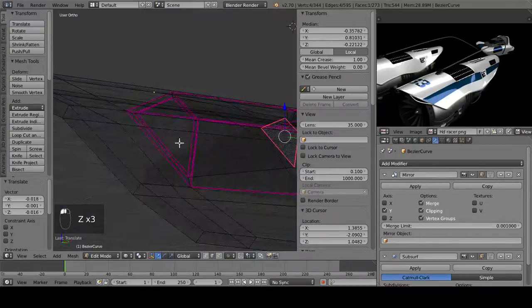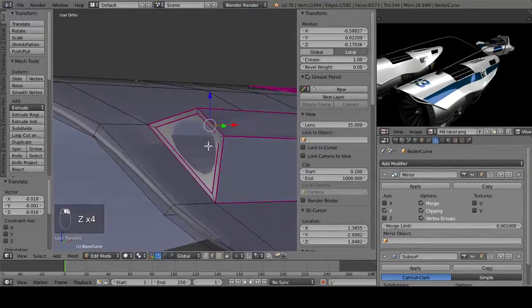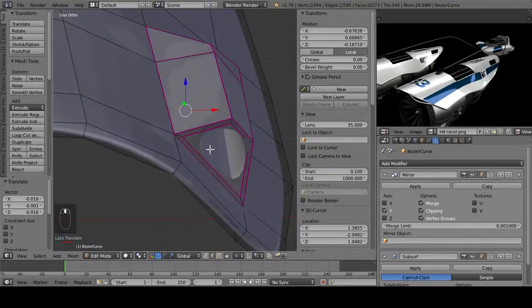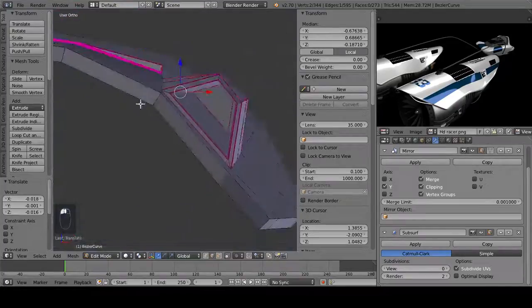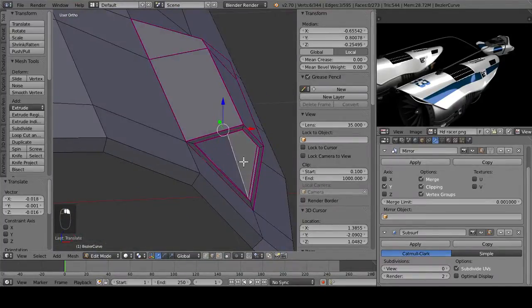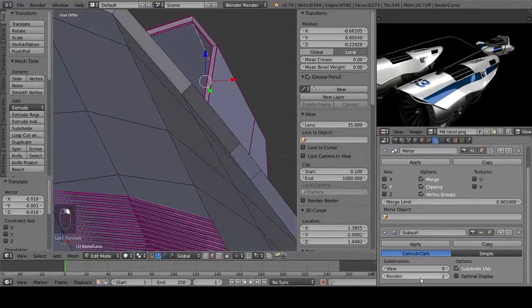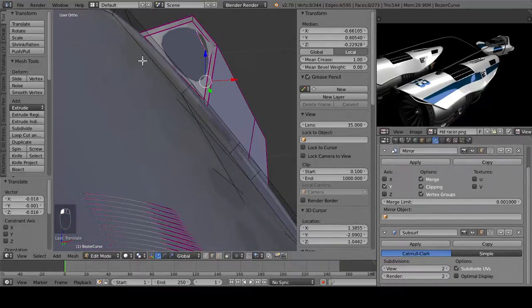And then because these edges are here, we have to crease the inside. I can't really get at it through here because I can't really see them. So if we go to our modifier tab, lower the subdivisions, you see here I can finally grab this inside crease, select all of those, increase the mean crease to 1.